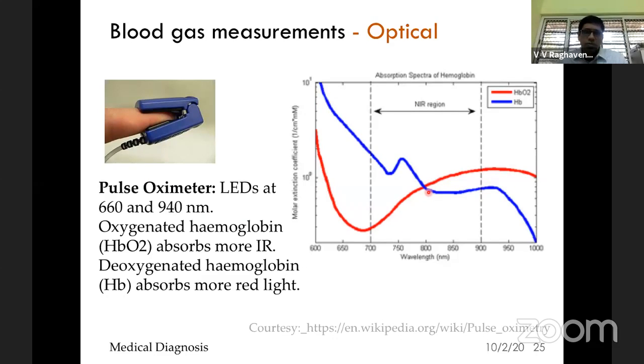So this is a PPG machine or pulse oximeter that is now widely being used. Here, what you see is a wired device. You actually have wire-free devices also in the market. It works on 2 LEDs and 1 single PD. The 2 LEDs are chosen such that the difference between oxy and deoxyhemoglobin at one wavelength is not much, whereas at the other wavelength it is very high.